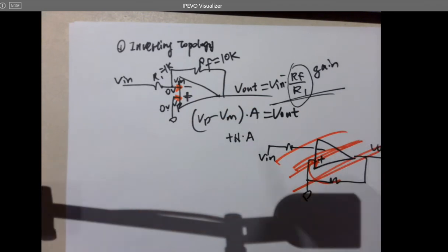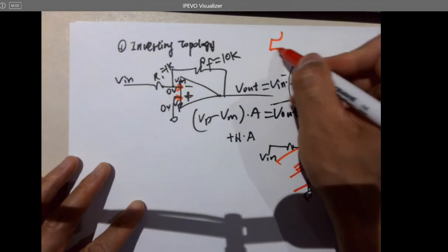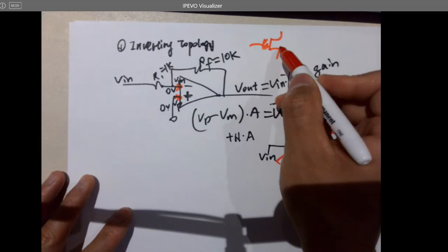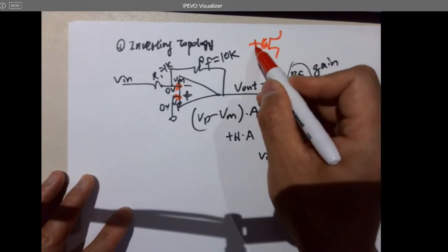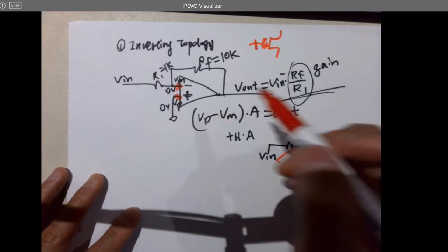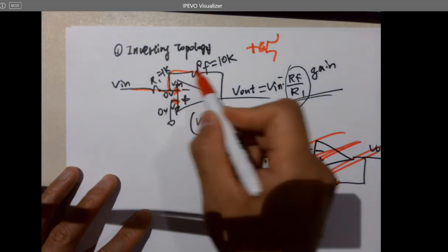If you want to think about that, it's literally the gate of the transistors, and there's a dielectric material, so it's not directly dumping current inside. So all the terminals are inputs of the transistors, they are gates. So currents are not flowing inside the OpAmps. This is something you want to memorize. Okay, keep in mind. So the current actually flows in that way.